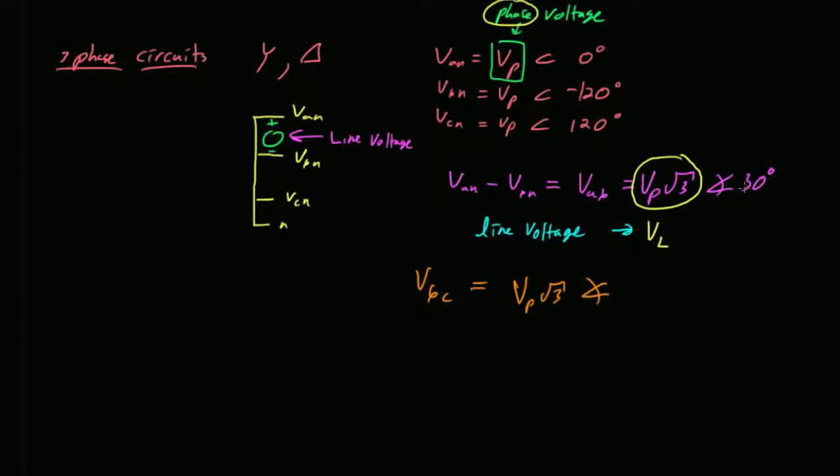You would expect it's always a third of the way around the circle. Between any two of the phases, it always lags by 120 degrees. So if this is 30, if you go back 120 degrees behind it, you should get back to what, 90? Negative 90. Thank you. All right, so that was A to B, B to C, and then the third one, of course, is VP root 3 angle. You go another 120 degrees back. What does that get you to? 210, and so on.